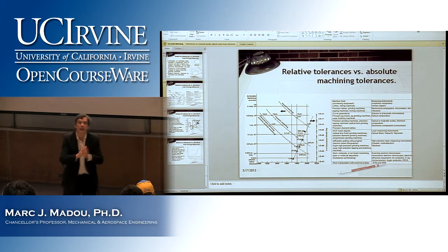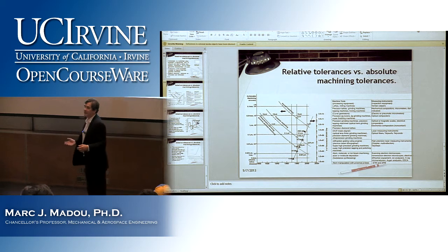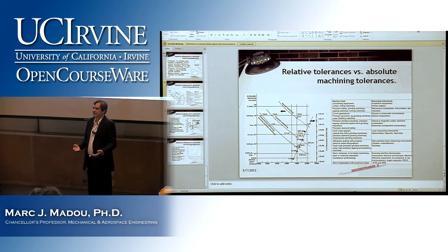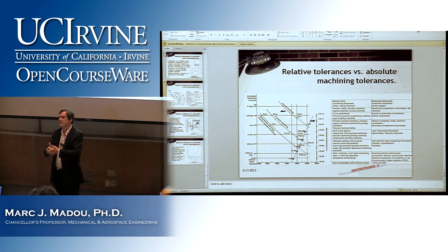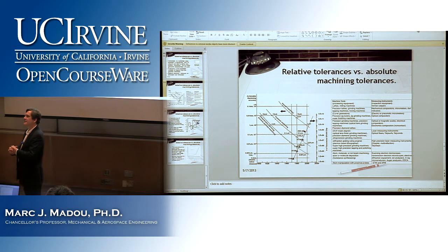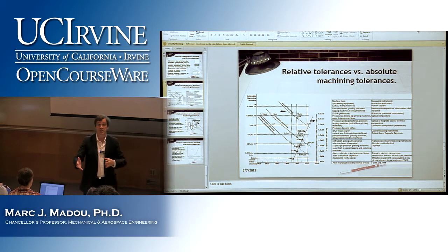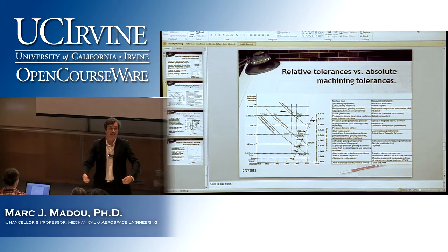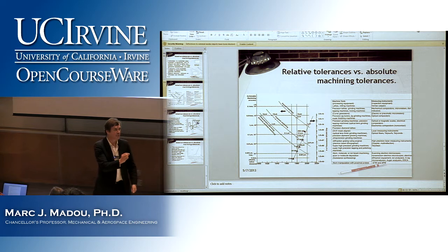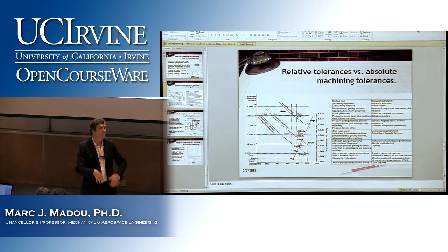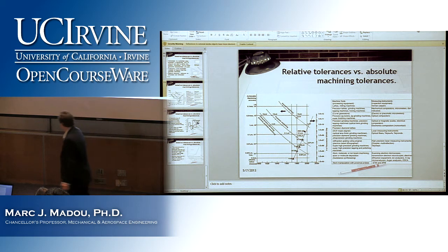But why? What's underlying there? And why lithography, which seems so different than mechanical machining, they are linked. The same thing allows progress in both fields. Do you remember what that is? You always have to work on a table. Yeah, very good. It's these XY positioning stages. And the better these get, and you can control the steps you can make, the better you can do your machining, be it mechanical or lithography. Remember that.